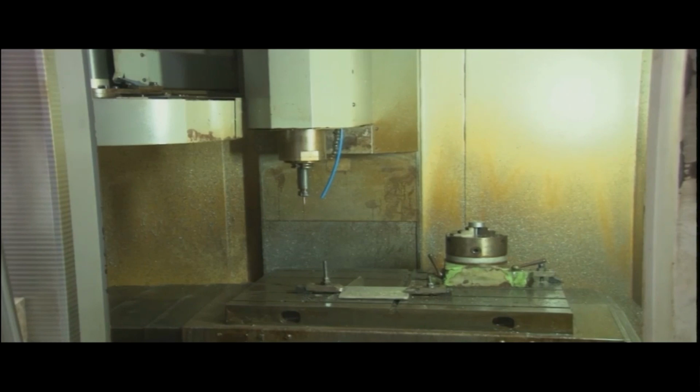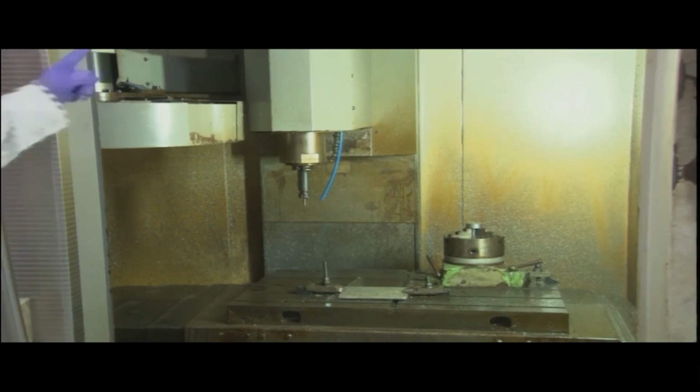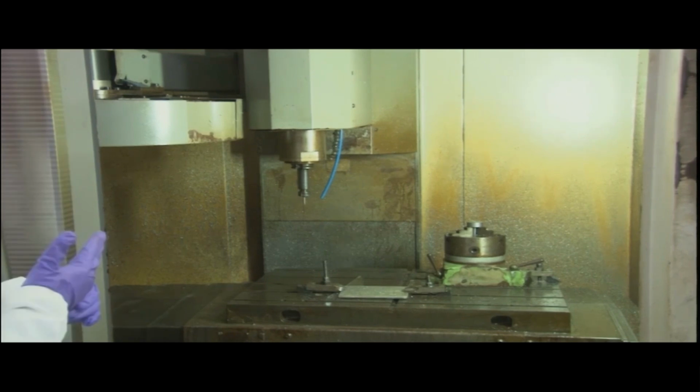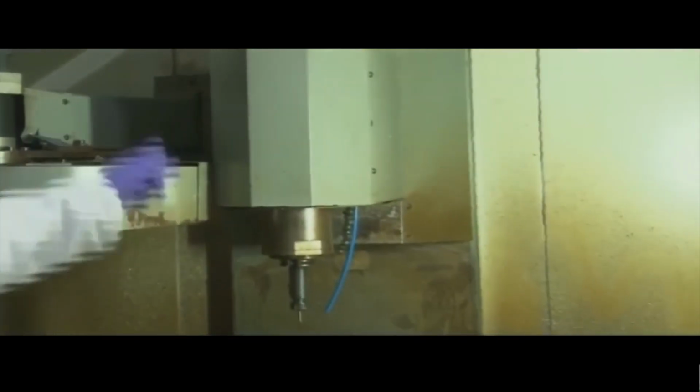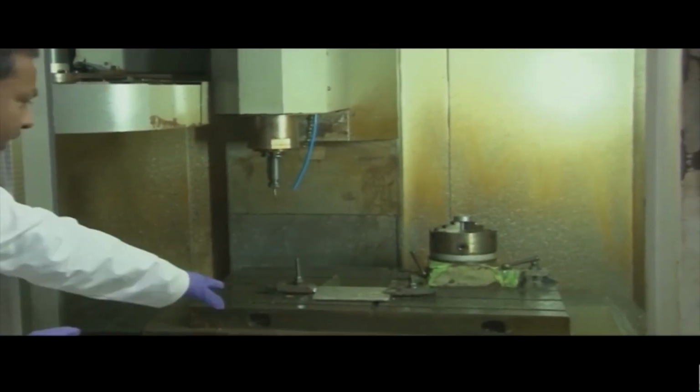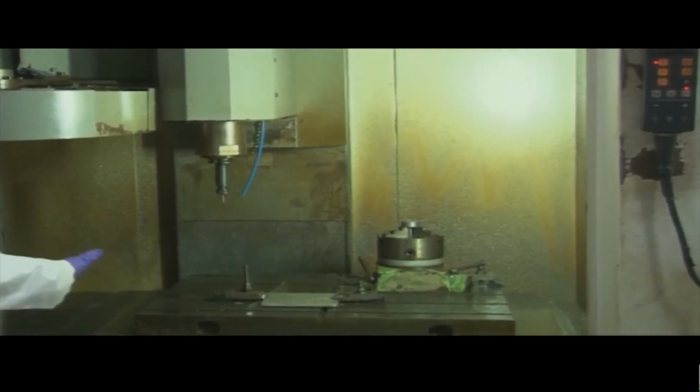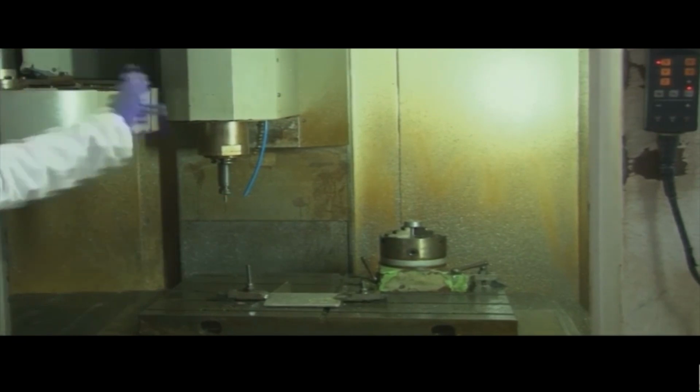A machine here, this machine is known as a vertical 3-axis milling machine. The milling machine can be broadly classified into two categories: horizontal milling machine and vertical milling machine. It all depends upon the orientation of the tool. In this, the tool is vertical. Tool is vertical means that movement of the tool is vertical in the Z direction, that is why it is known as vertical milling machine. In the horizontal milling machine, the tool direction is towards X direction. So, in this, the Z axis can go up and down and the tool goes up and down. It is vertical to the bed, that is why it is known as vertical milling machine.